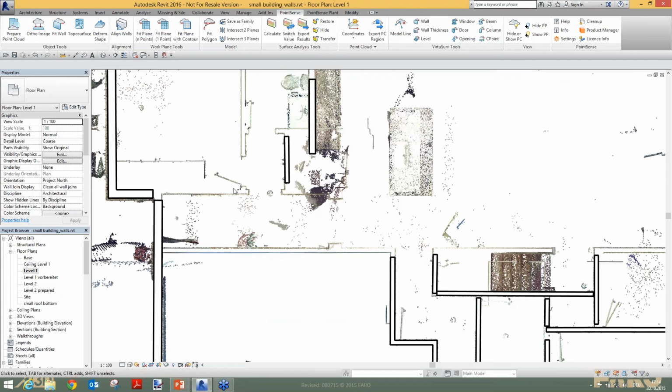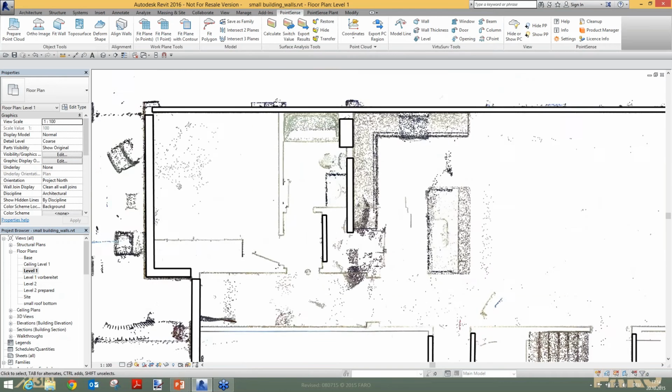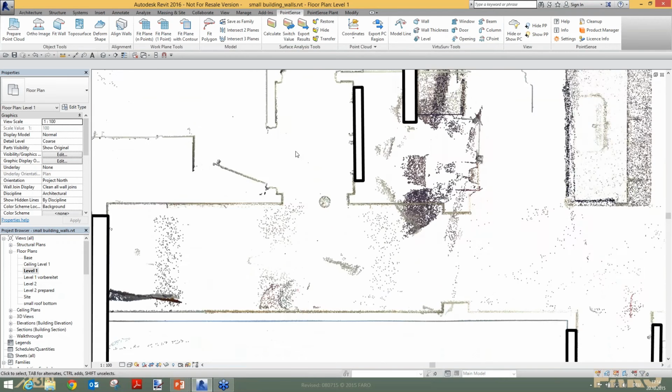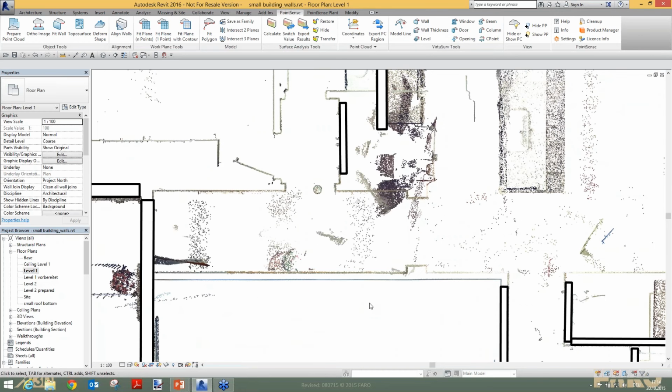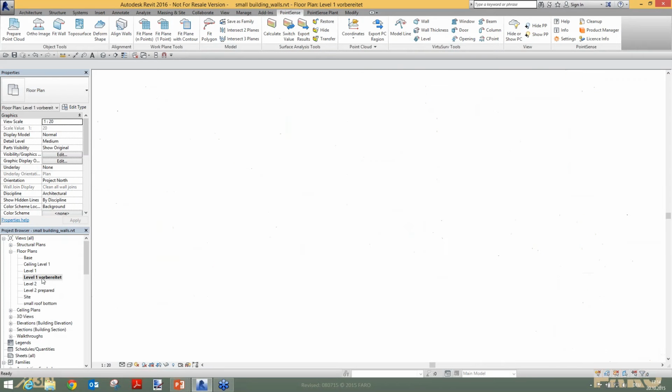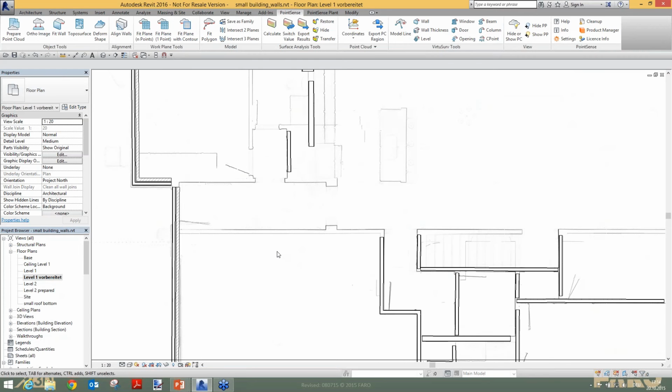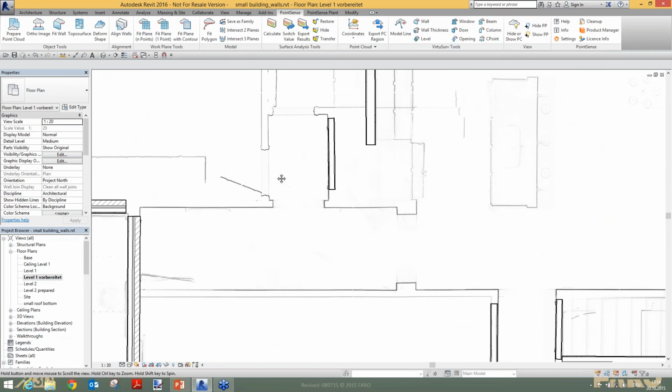Okay. So, and you can see here the points of the walls from the point cloud. And the first thing we do with PointSense is a preparing process. Preparing means we calculate from the point cloud a so-called ortho image, and in this ortho image we are able to fit the walls much faster than in the point cloud. And as a side effect, you can see it here.